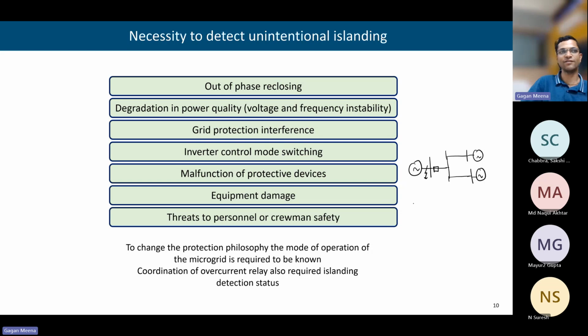So whenever they have to do any kind of fault isolation, they have to ensure grounding on both sides of the conductor. Let's say this is the section of that feeder. They have to ensure that grounding chains are there on both sides.